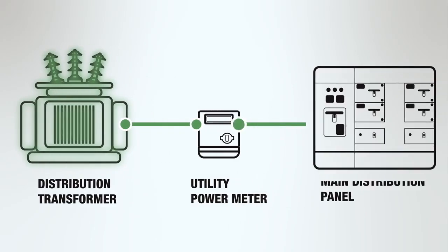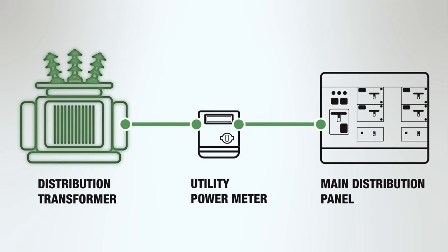The power is fed to the main distribution panel, which may further transform the voltages to suit the specific power needs of office equipment or other mechanical devices. This equipment contains protection circuitry such as fuses, circuit breakers, and switches to prevent failures from bringing down the entire system, or to allow circuits to be switched off for maintenance.